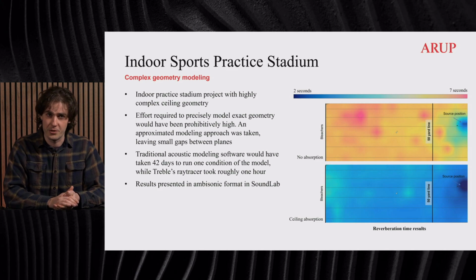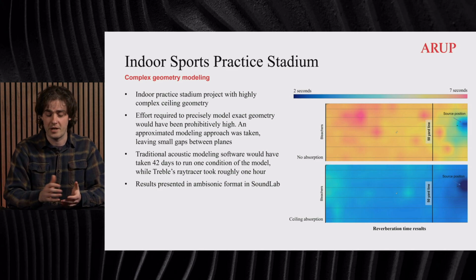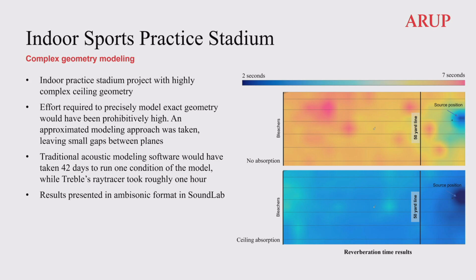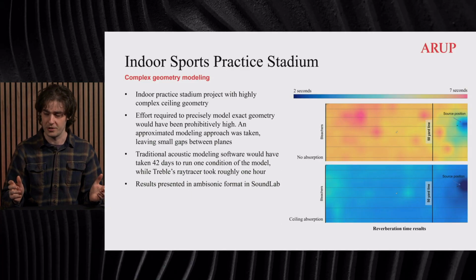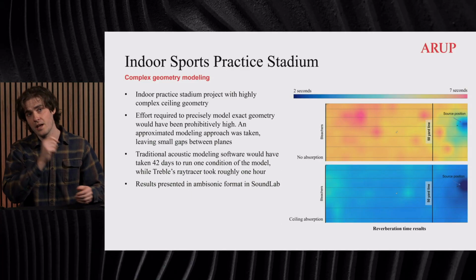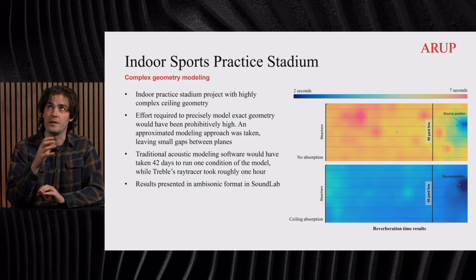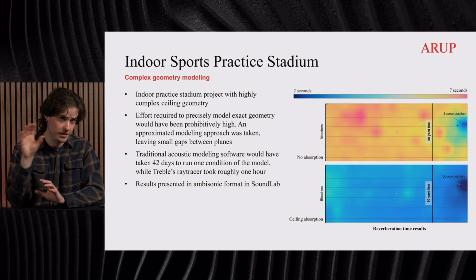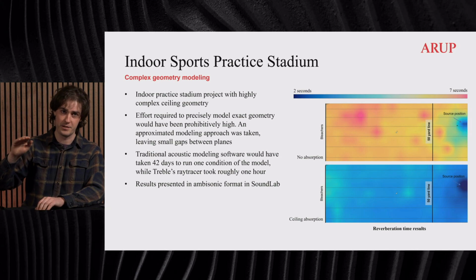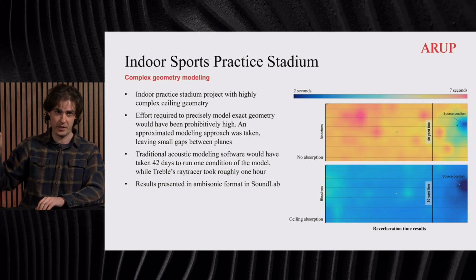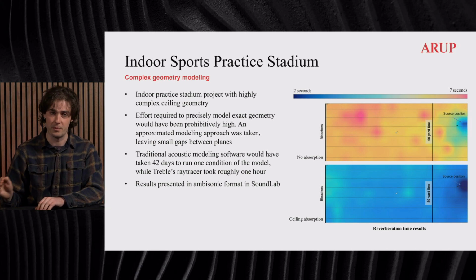So specifically what was so tough about this one is just modeling this complex geometry in a large space in a way that won't make the software freak out and take a million years to process your data. So the architectural model we received with that complex geometry had a lot of little gaps and holes everywhere, which we all know usually acoustic solver software doesn't like. But to model it really precisely in a completely airtight fashion with those lattice beams being flush against the roof in every location was an extremely time-consuming process.